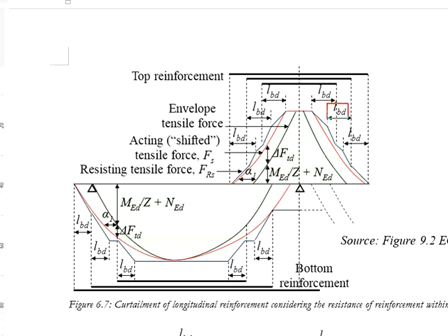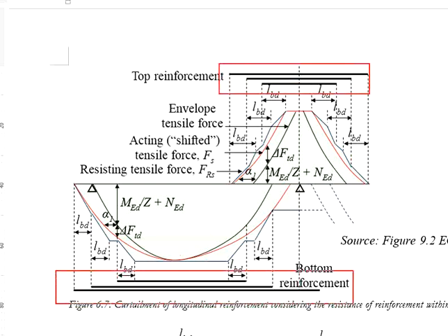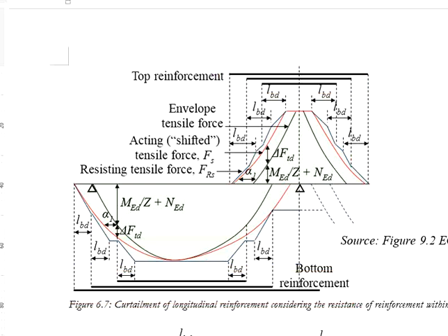In the case that they are overlapping in terms of the anchorage length, the stress developed within the second group of the reinforcement now can help to add up the resistance here. That's why the resistance here ends up being rather crooked. Therefore, the bottom line is you will need to do trial and error and provide the reinforcement in a way that your resistance is always greater than what is required.